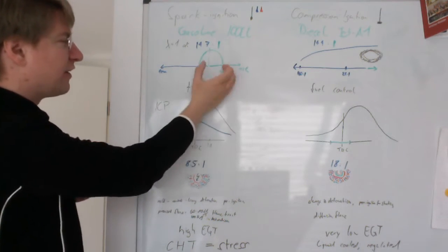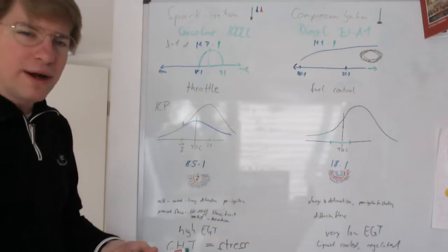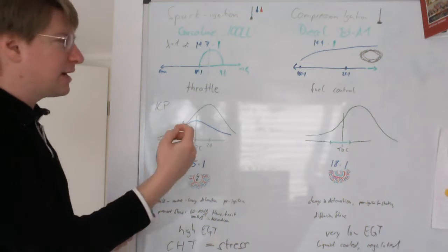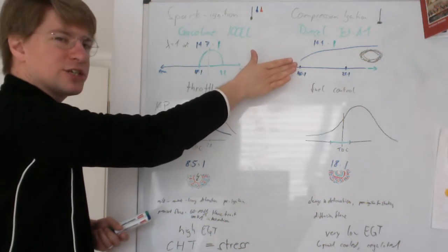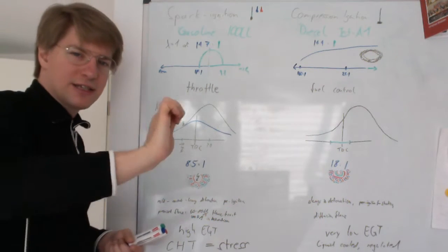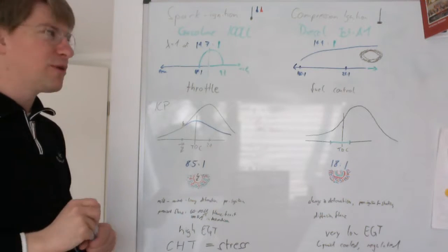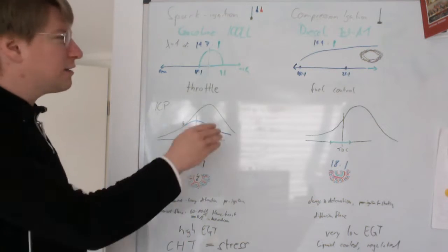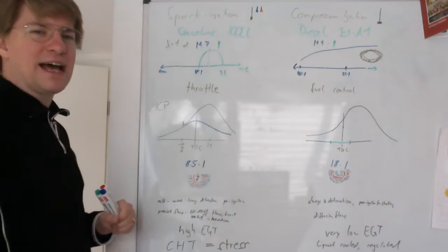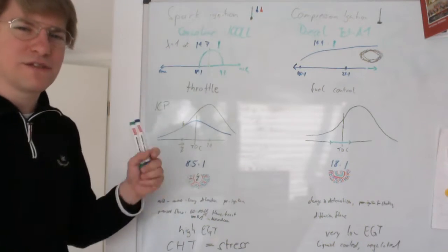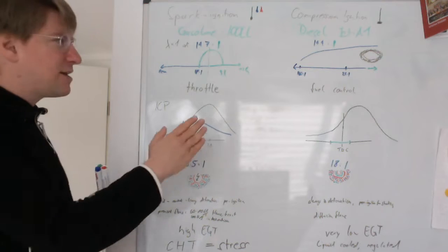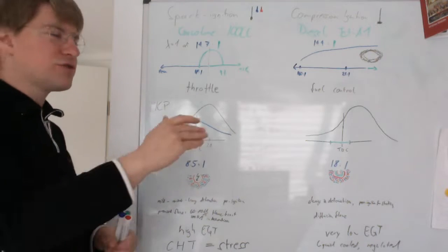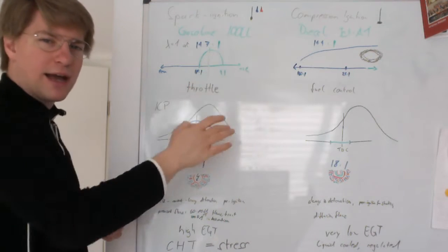And on this graph, the lean mixture, so more air, less fuel, when you pull back on the mixture control, when you pull back on the red knob, is on this side. And the rich side, so more fuel, less air, is on the side where you push in the red mixture knob. And what you will see is that around this optimal 14.7 to 1 mixture, the curve is kind of flat. So as long as you are in the general vicinity of this 14.7 to 1 ratio, the engine runs quite good. If you go over to the rich side, it continues to run fine for some time here.